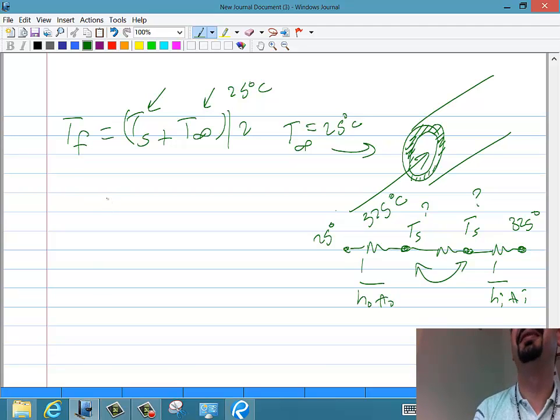Well, of course you can assume it wrong, right? This just makes the solution longer. So let's assume someone would say, well, I think it's at 50. And you get the properties at 50. And then he calculates the temperature. Eventually you can calculate the temperature to check on your assumption. Yes, it's not required to calculate the temperature. What we wanted was Q. But you have to check on your assumption. Anytime you assume something, you check on it. So we assume 50 degrees and we calculate and it's 80, for example. That's not a good assumption then. Then you have to revisit again and say, let's assume 80.